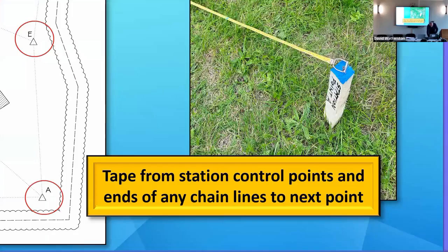So this here is a picture of a survey control station, and the tape's hooked on the top of it. And you can put another peg with a tape on it and pull that and accurately measure from these 2 pegs, and that would be your base station.